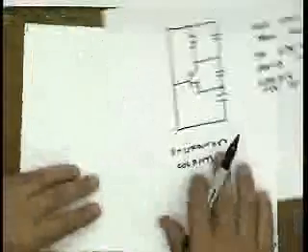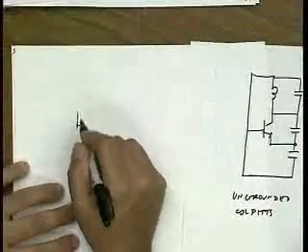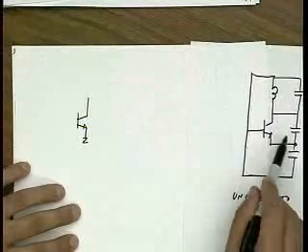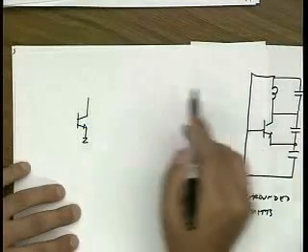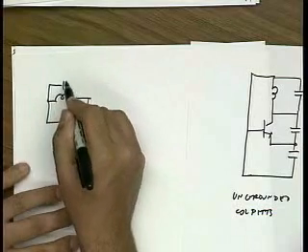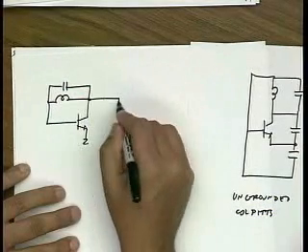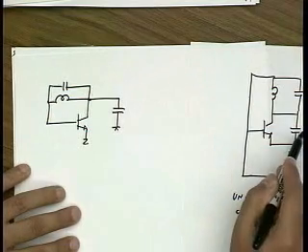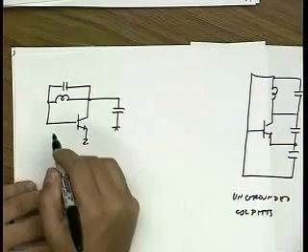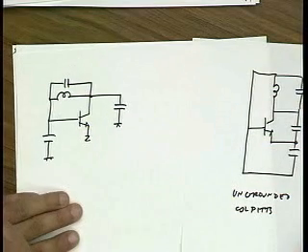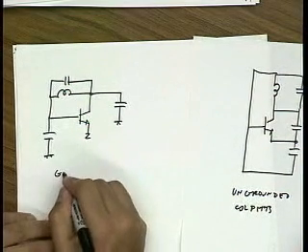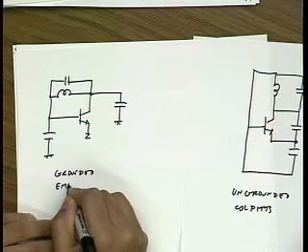And for a while, people were doing this without realizing it and inventing new oscillators. For instance, let's say we ground the emitter, okay? So let me show that over here. If I ground the emitter, then this position now is floating, so this becomes a feedback tank like this. Have a cap from here to ground. That's this cap. And then this cap is from base to ground. Okay? So this is a grounded emitter.